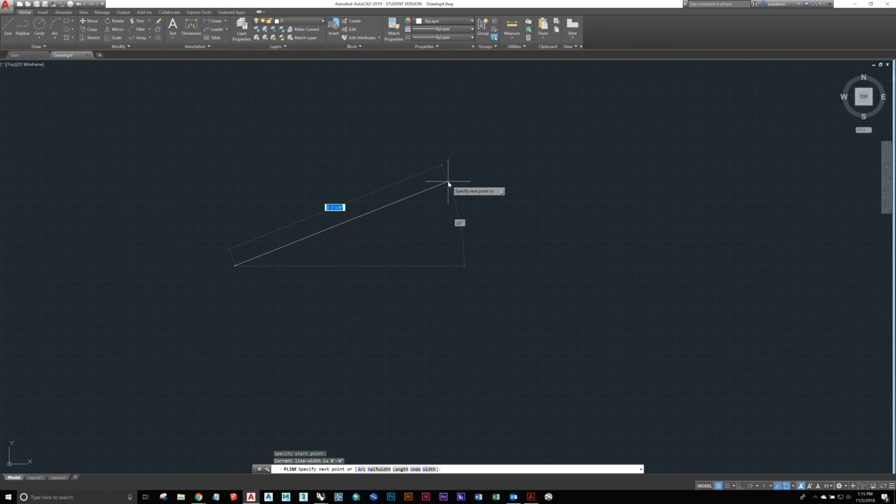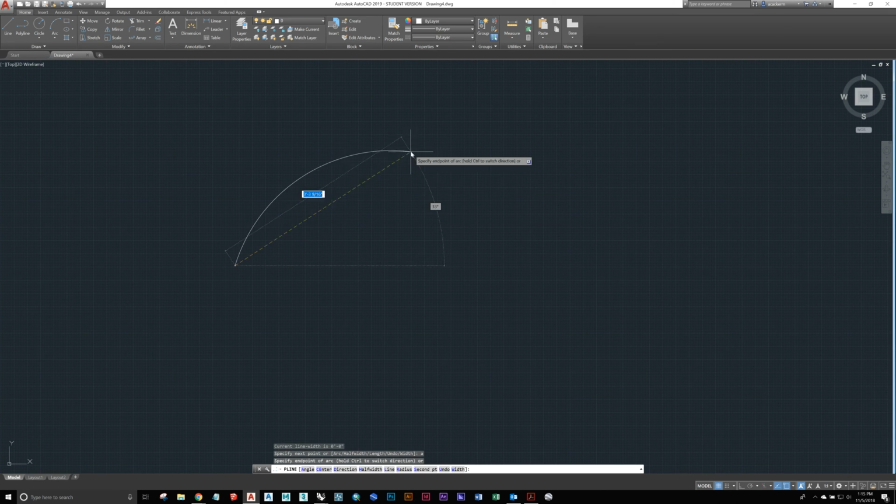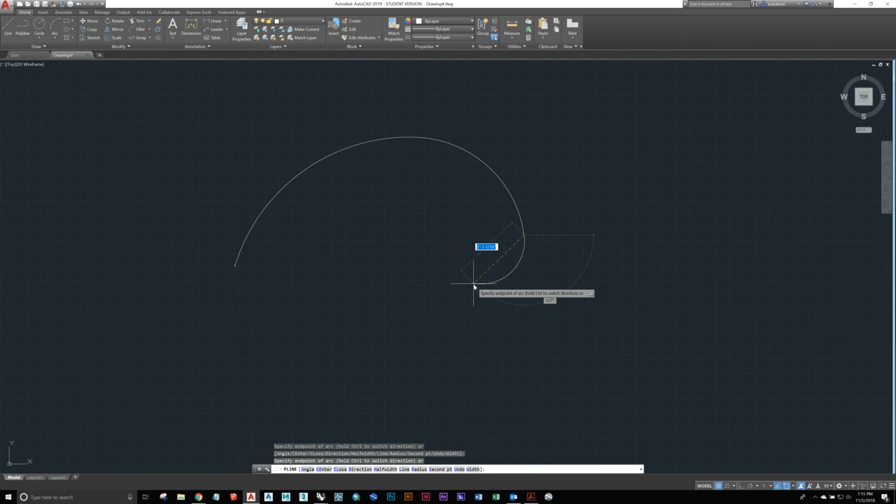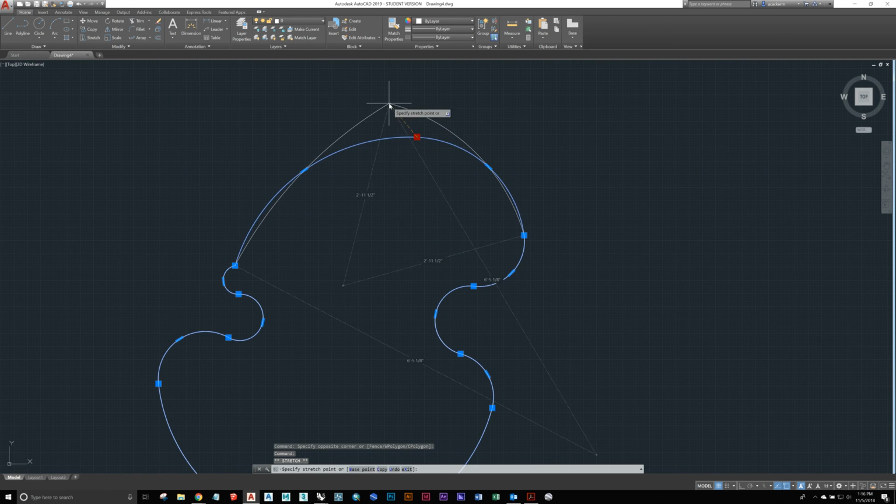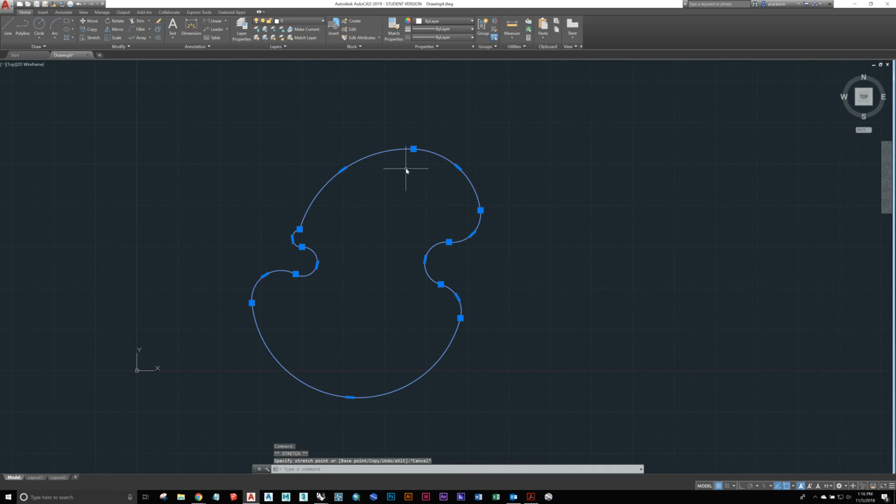Also, when I go to draw a polyline, I can start with the first click. Before I make the second click, if I type A, enter, it will create this sort of continuous arc where each line connects very naturally to the next. And that's that polyline. And then these don't behave quite as naturally once they're drawn. You can adjust those center lines.